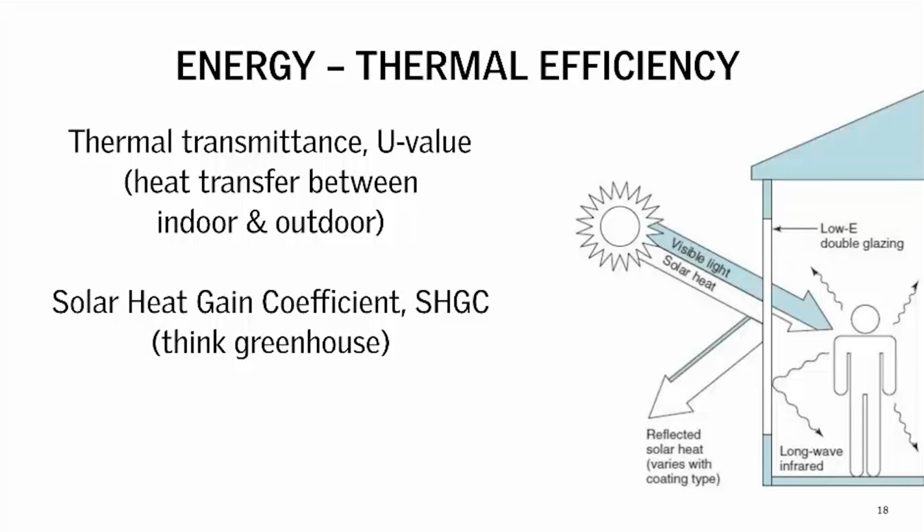And that's important, I'll say, for two reasons. One, Monica mentioned last week that we can get 2 to 3 times more light through a skylight than a vertical window. That also correlates that we can get more heat in the summertime through a skylight. So we need to keep that in mind, because high performance buildings, really airtight, well-insulated buildings, often are more susceptible to overheating. And this happens even in Denmark, where our head office is, so it's going to happen in Canada as well. So we have to be smart about how we're using windows and skylights in high performance buildings.